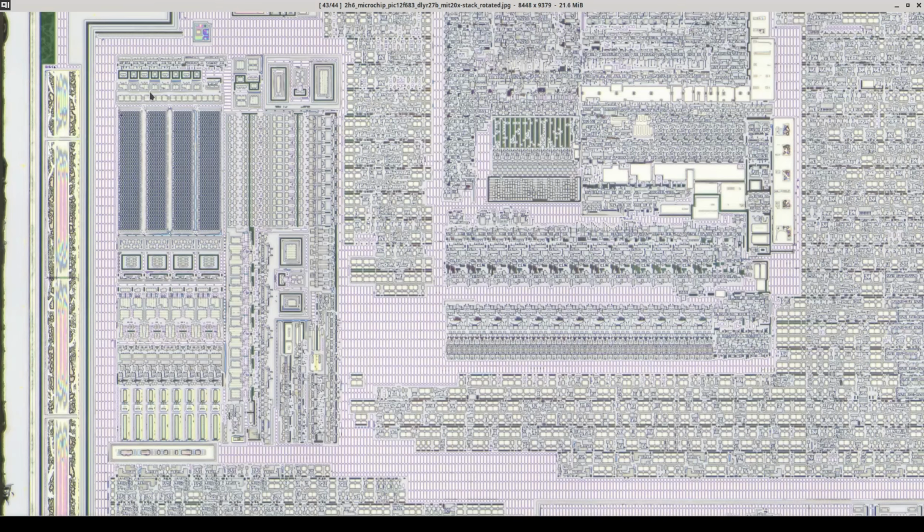this array, which is a very small array of the same bit cells used in the main flash, and then has a bunch of other analog circuitry around it, and we can see 8 big capacitors down at the bottom here, also suggestive of high voltage generation. And so this is clearly the data EEPROM.